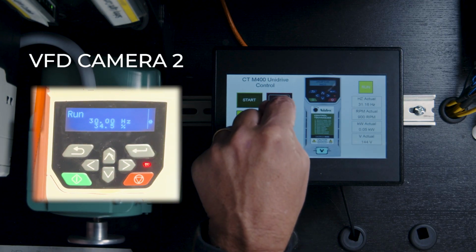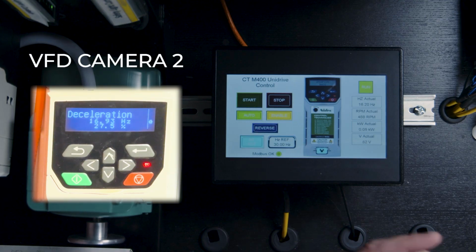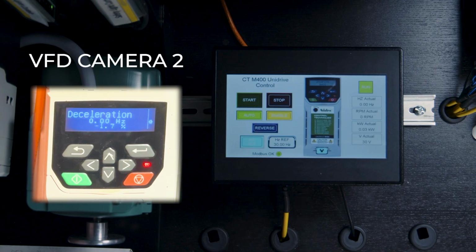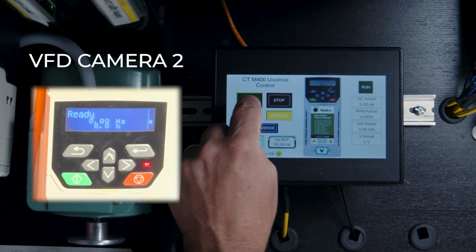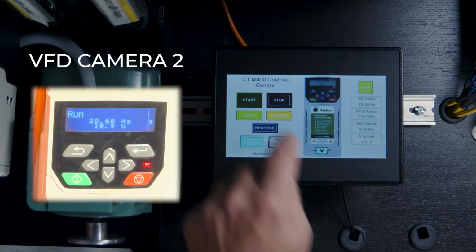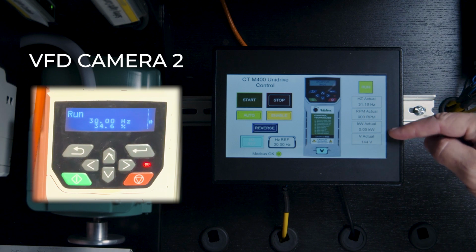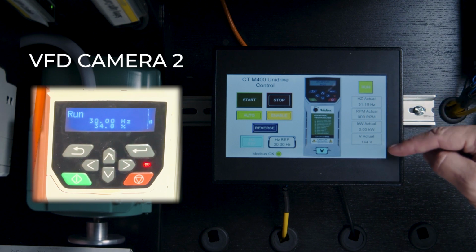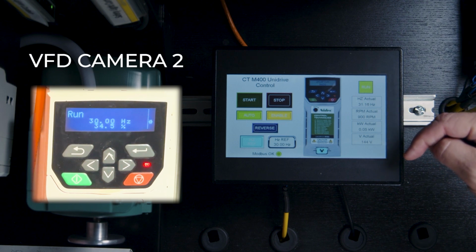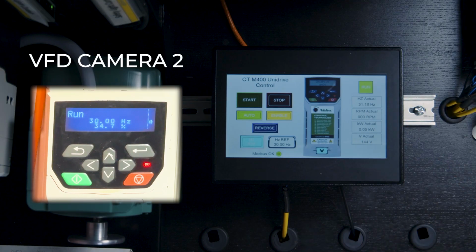All right, and then I can go ahead and stop this guy here. So as you can see, everything's working great. Oh, one other thing I want to mention. Let me go ahead and start it back up again. We're getting what look like legitimate values over here, even though we're only reading the lower 16 bits of those 32-bit parameters in the case of RPM and kilowatts. So I think this is working just as we would expect, even though for those particular 32-bit parameters, we're only reading the lower 16 bits.